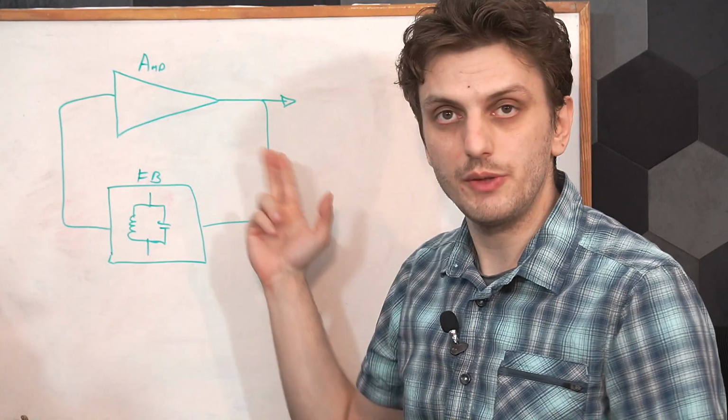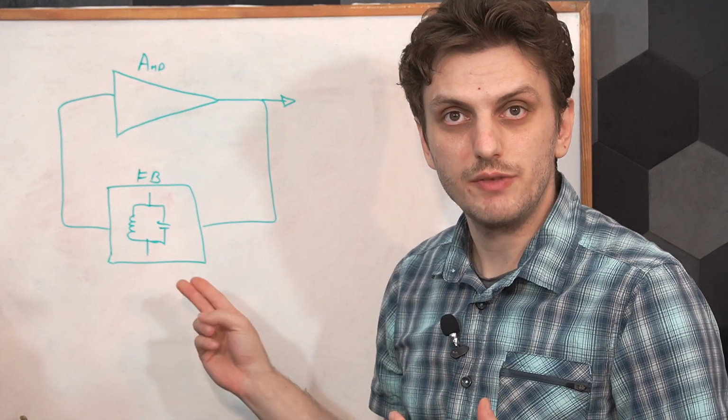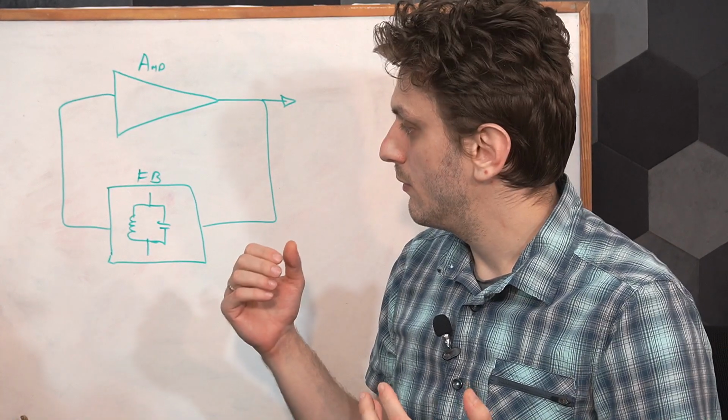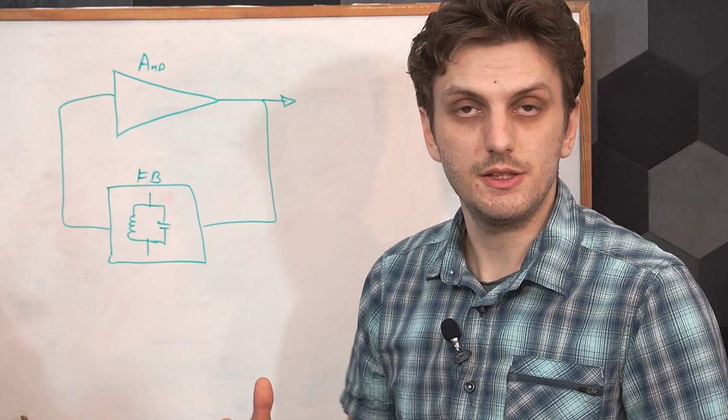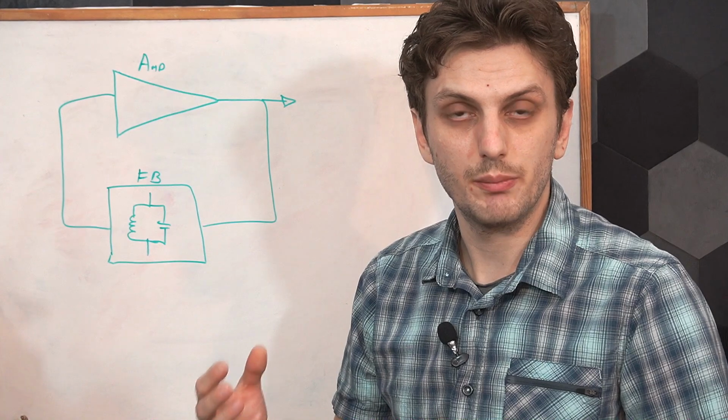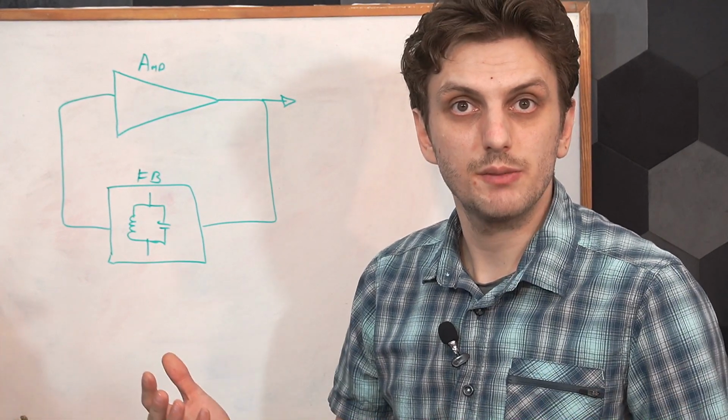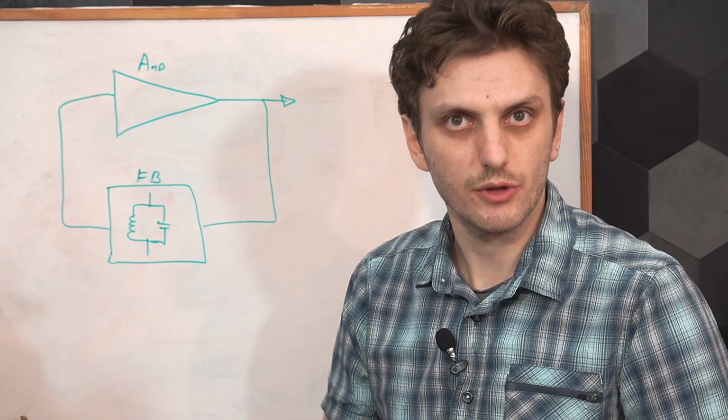So to change the output frequency, we need to change one of the elements of the filter. Most commonly, the capacitor is the one that is being varied. And an easy way to make a voltage-dependent variable capacitor is by using a varicap or varactor diode.